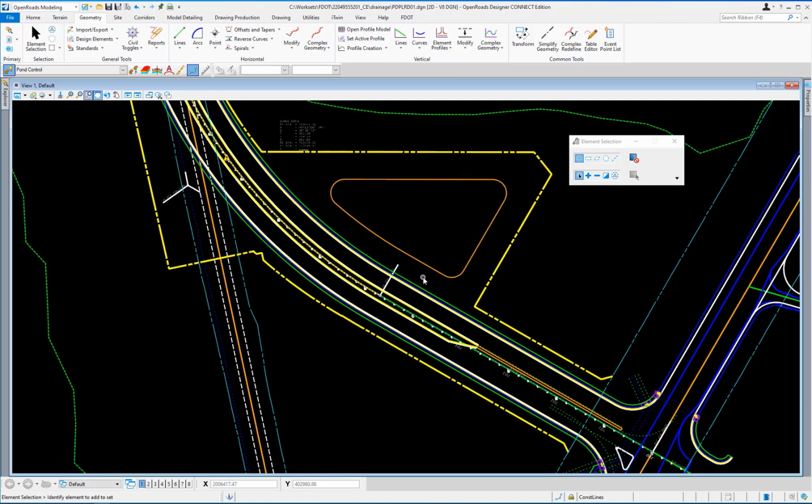Using the Element Selector tool, left-click on the green dashed Existing Ground Boundary element. Hover over the line to cause the pop-up menu to appear. Select the middle icon to set this as the active terrain model and left-click in the Open to clear the selection set.